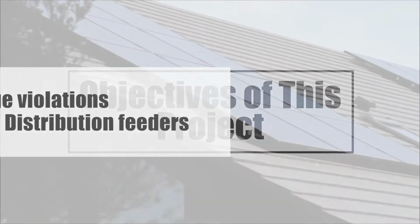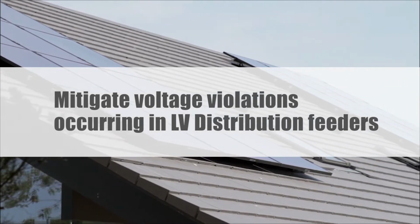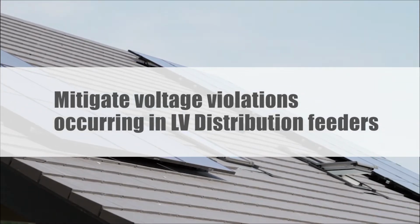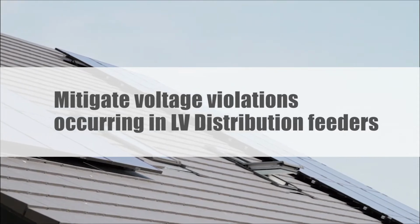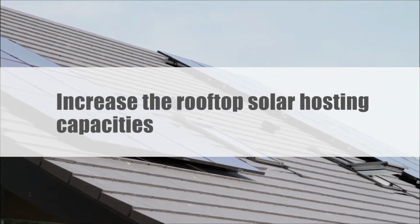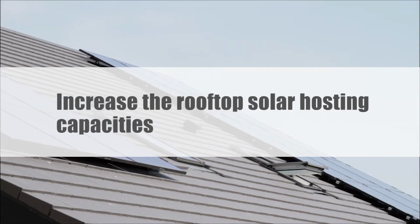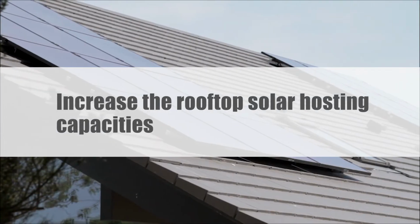Let's talk about the objectives of our project. We are expecting to mitigate voltage violations occurring in the low voltage distribution feeder. The upper limit of the PCC point voltages in the feeder will be maintained at or below 1.06 per unit as per the SLS 1522 standard of 2016. Also, we are expecting to increase rooftop solar hosting capacities. This will be done by distributing solar generation throughout the day, avoiding voltage peaks.